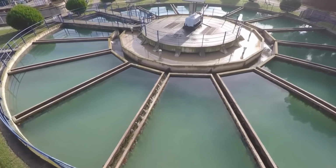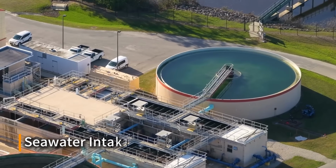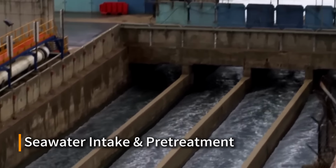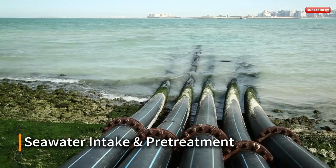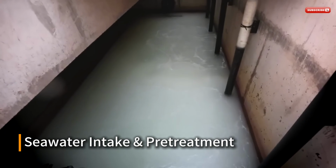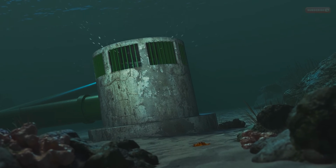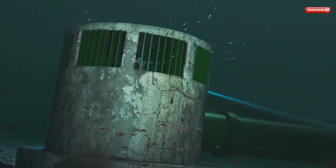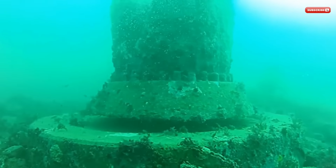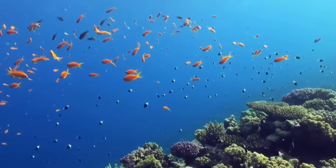The process begins with bringing seawater into the plant. Before any salt can be removed, the plant first needs a constant supply of seawater. In many coastal plants, large intake pipes extend offshore and draw seawater toward the treatment facility. At the entrance, screens stop larger debris, seaweed and marine animals from entering the system. The intake velocity also matters. If water is pulled in too quickly, fish and other organisms can be trapped against the screens or drawn into